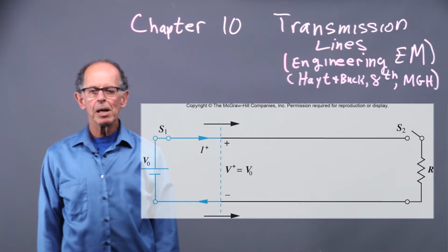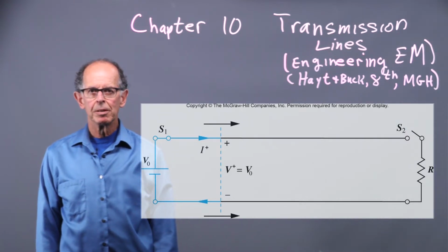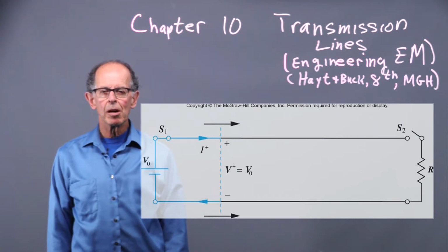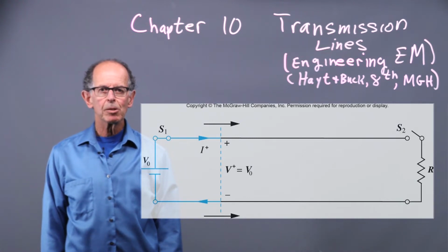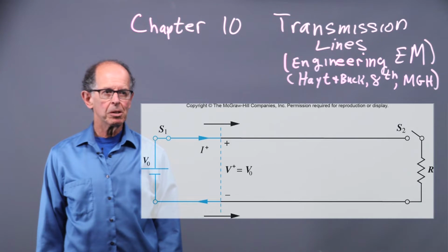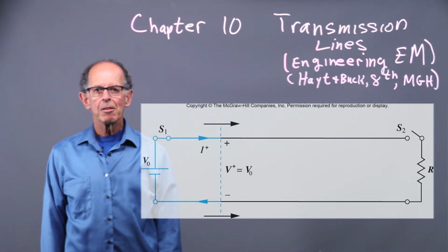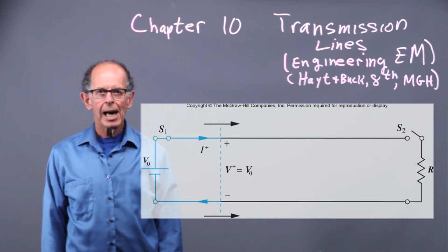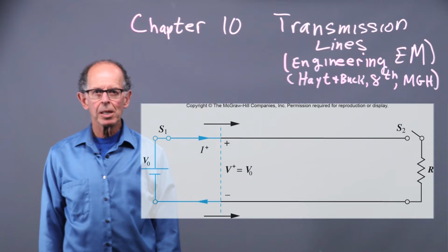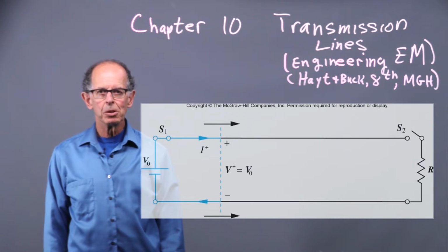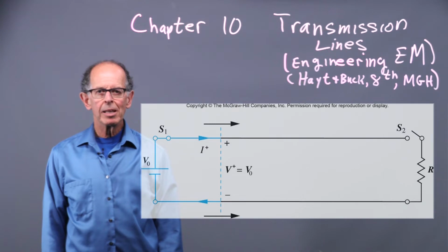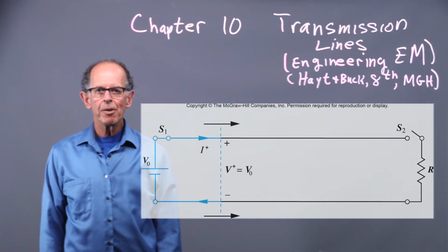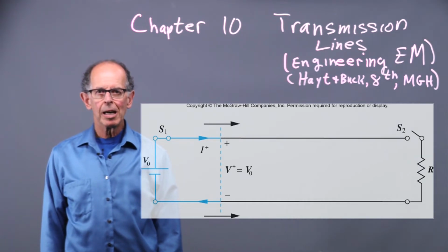Well, the blue represents a moving wave in the line. It's launched at the time which the voltage is switched on. So when the voltage is switched, at the point of switching, it goes from 0 to some V0 volts. That is not DC, it's a transient. It has frequency, and it's that transient that launches the wave. So behind the wave in blue, everything's happening and the line is getting, as they say, charged up. To the right, all in black, the wavefront, as indicated by the dotted line, has not yet moved.